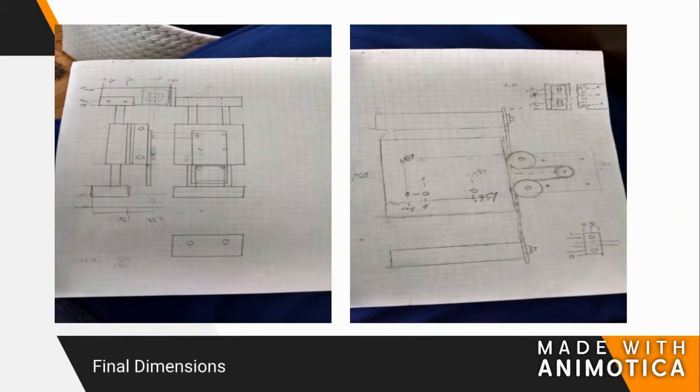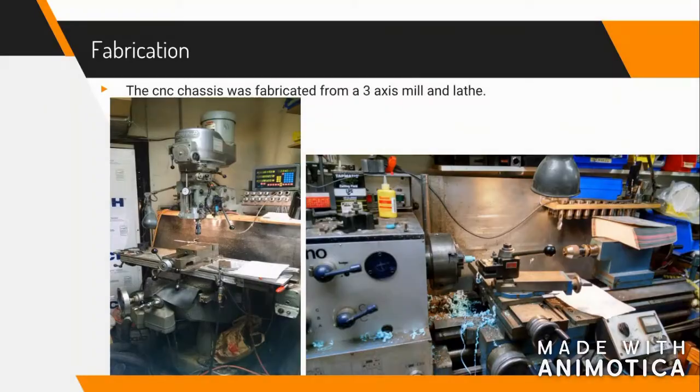These are the final dimensions of hole patterns and sizes for parts that we machined. Every square on the grid pattern corresponds to 1/4 of an inch. All parts were either scrapped from packaging machines, such as linear actuators, or created on a 3-axis mill and lathe. These machines were home accessible for one of the team members. The materials we used were Delrin, acrylic, aluminum, and steel.